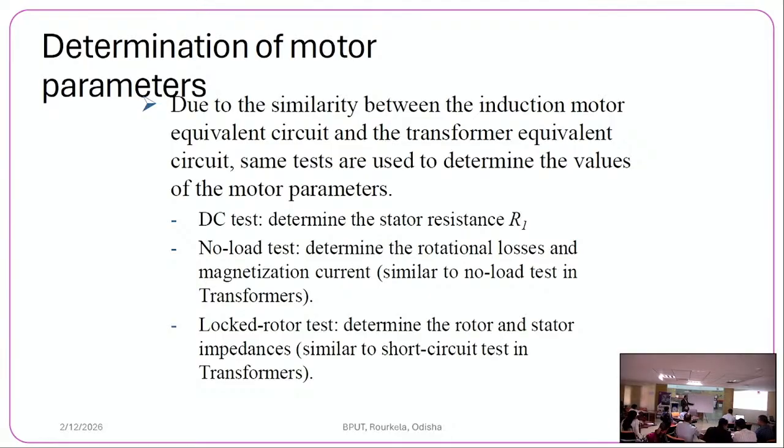If slip is nearly equal to 0, then R2 by S is infinity. Infinity means open circuit, and no power goes there. So it is the open circuit test, or no load test.